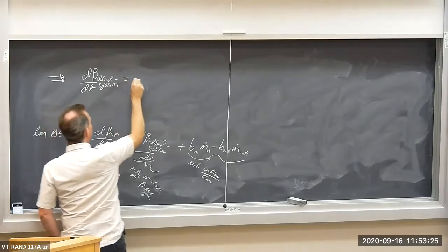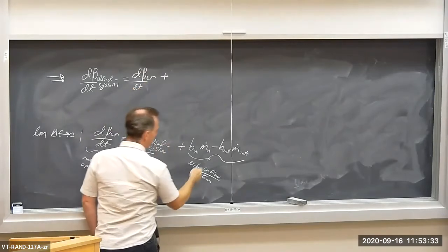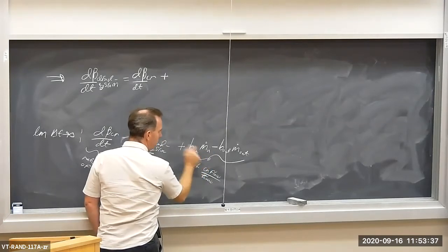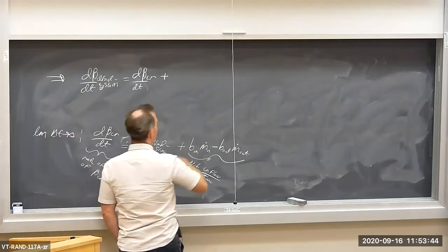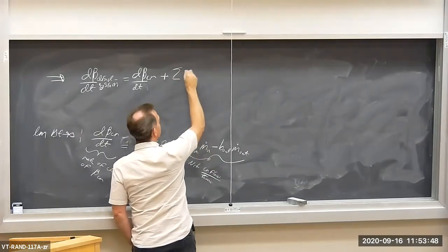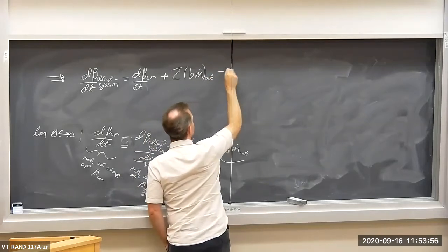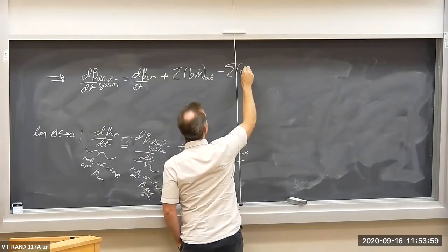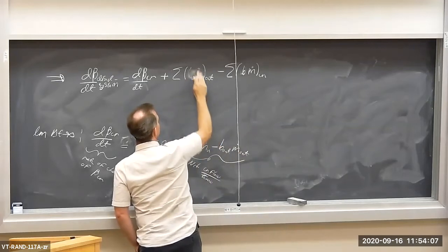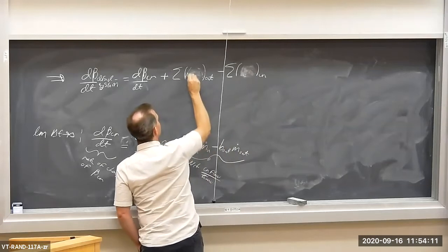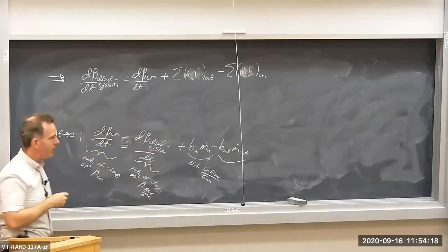system, is equal to the rate of change of beta within my control volume plus, now the signs are going to flip on the beta out and the beta in terms, the flow of beta in and the flow out, because I'm going to put this over on the other side of the equation and flip the whole equation. So with multiple inlets and outlets, the sum of m dot beta out minus the sum of m dot beta in. I think I'm going to put m dot beta first. m dot beta per unit mass, outlet minus inlet.